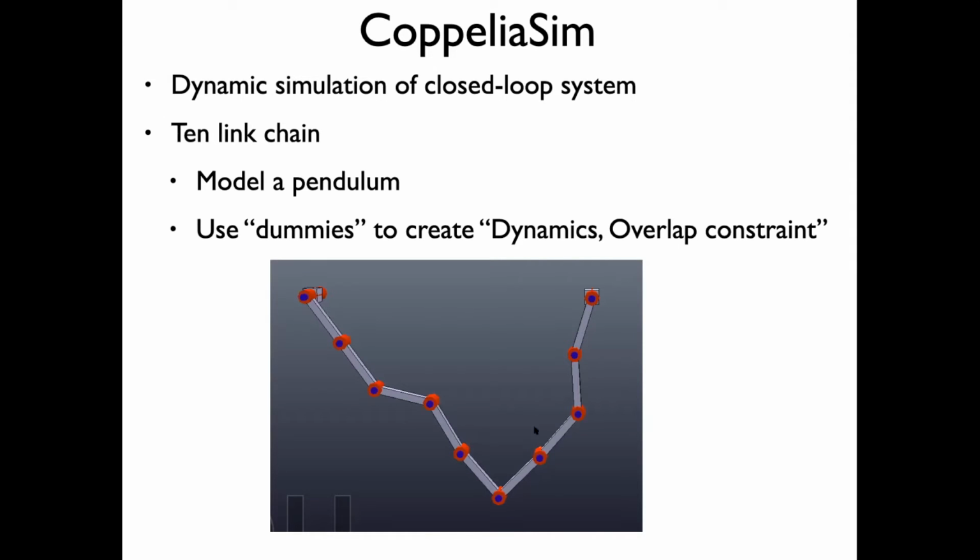Basically, you make the pendulum from one hinge point, and then you keep the other end free, and then you tell CoppeliaSim that that point is actually constrained to a hinge joint over here, and then it does its own computation to ensure that the loop constraints are satisfied, and it will do the simulation. Okay, so let's get started.